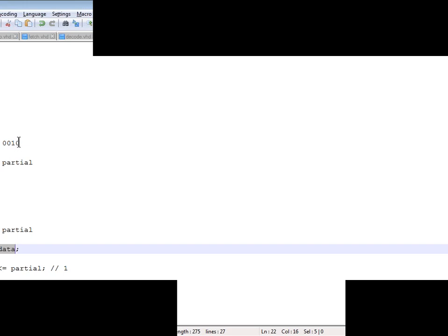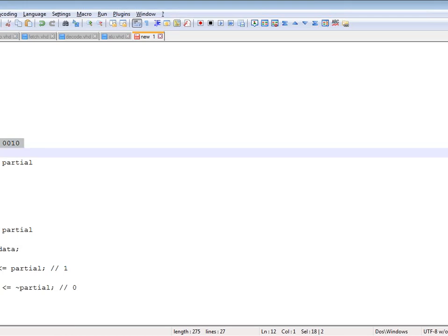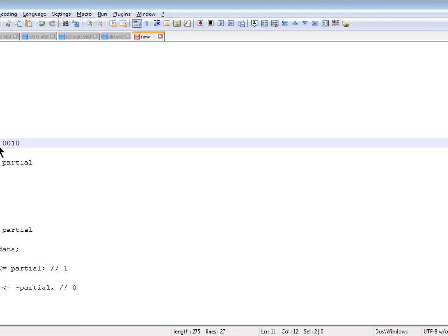So it will start from the MSB. This MSB bit will be XORed with the next bit. Then the result will be XORed with the next bit. Then the result will be XORed with the next bit, and so on and so forth till we get a single bit out. So this is called the unary reduction operator. In that case, you don't need a for loop. This single line will give you the output.